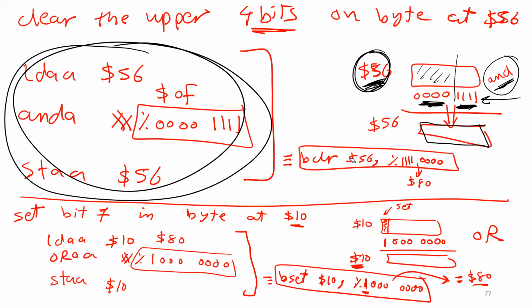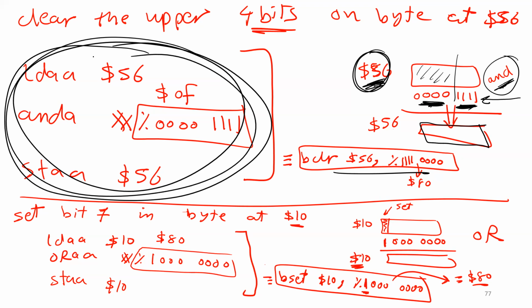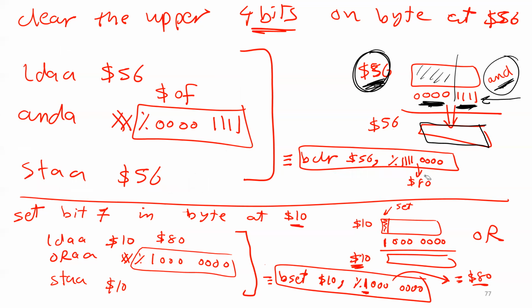Okay, so again, this instruction is going to do the same thing as these four instructions. But I suggest, it's much easier, you can just use this instruction all the time. There is something very confusing to the students here. Please listen to me. Here, the number I have to select, I have to put zeros to clear these bits. And the bits I don't want to change, I have to put ones, because this is how logic AND works, right? But this one, I'm not doing logic AND here. This is a different one. This one is gonna clear some bits, okay? So I'm not doing logic AND.